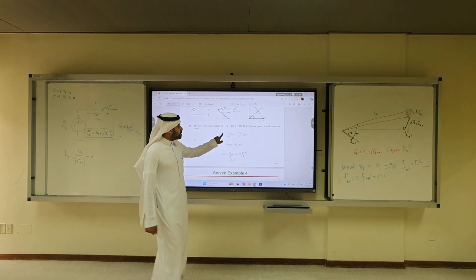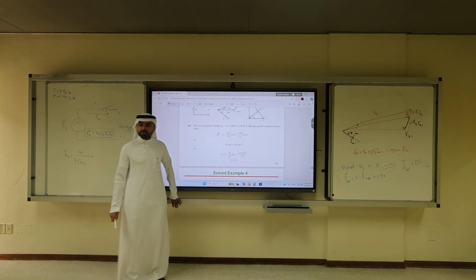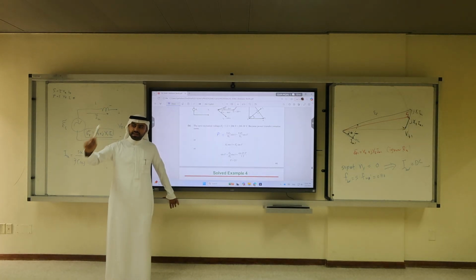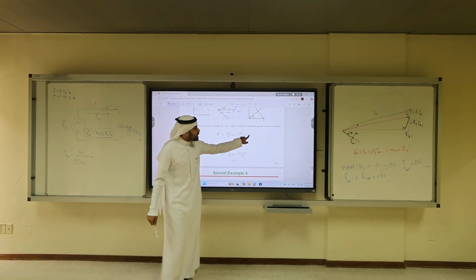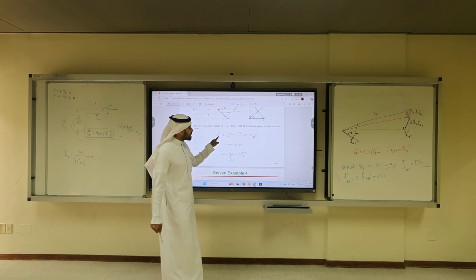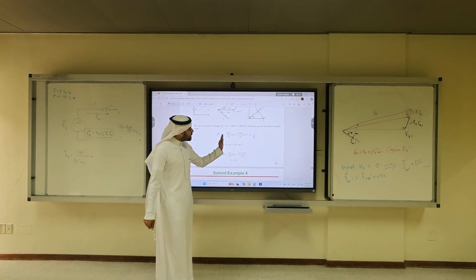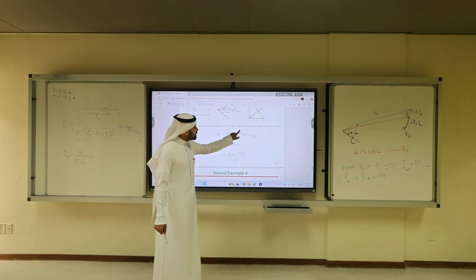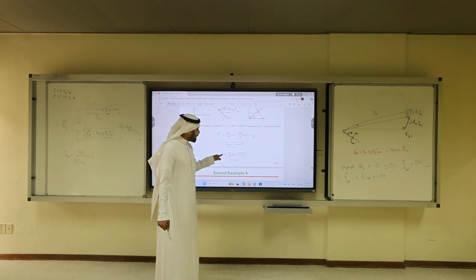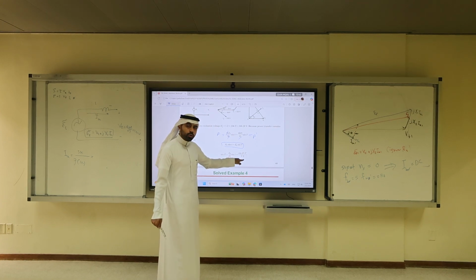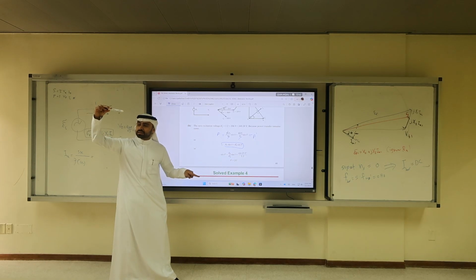What is this equation? This is the equation of the real power. You remember it? E times Vt over Xs sine delta. If I have the two powers the same, P and P prime, where P is for part A and P prime is for part B, I can equate those two numbers, cancel Vt, and I can write this equation. So I can actually calculate the new delta if EF and EF prime is 1.2 times. So sine delta prime is sine 25 over 1.2. By calculation, your torque angle would drop by 4 degrees.